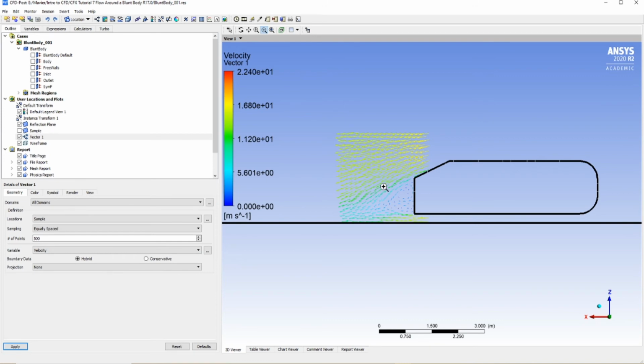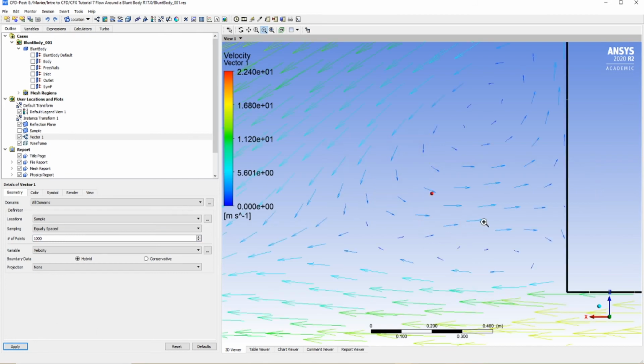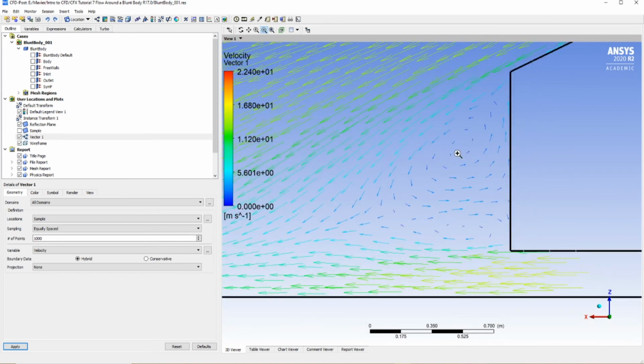But if you want even more points, like we did, and we see a lot more points, and you can actually see how it improves the visibility in the recirculation region, because we can clearly see two recirculation patterns, one that goes counterclockwise and is larger, and one is a little bit smaller one. It's almost like it's squished and is going in the clockwise direction.